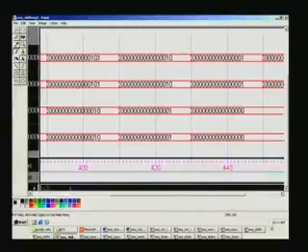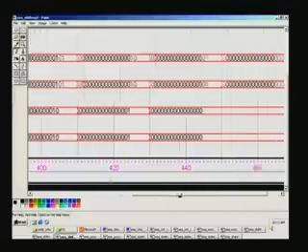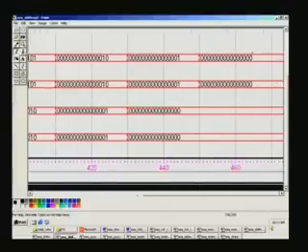You can see 101 here, all are zeros, and here all are zeros. This 1 will get dropped. So, what you have is 10 here, and then this 1 will move here as shown here, and finally that one also will disappear. That is how you see a shift register working. So, next we will move on to